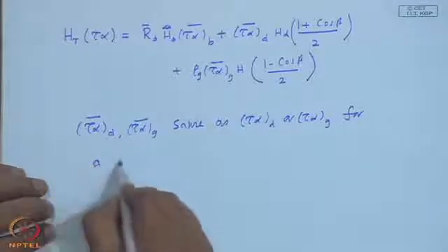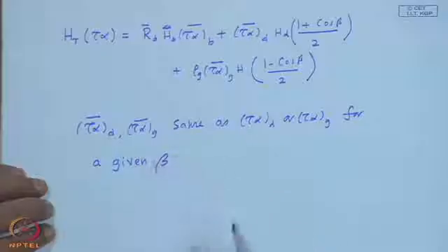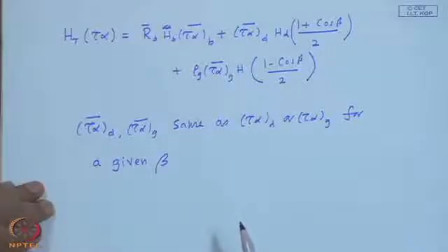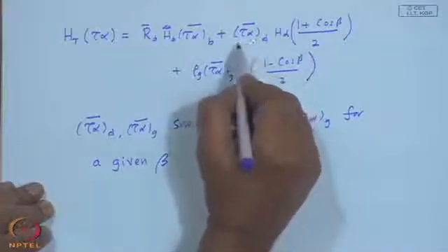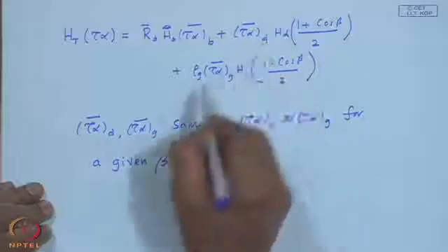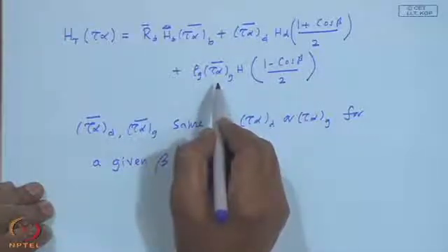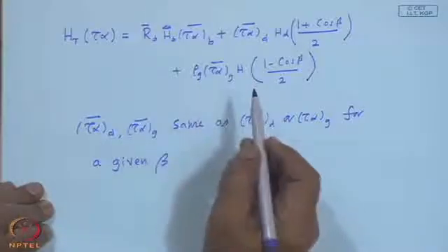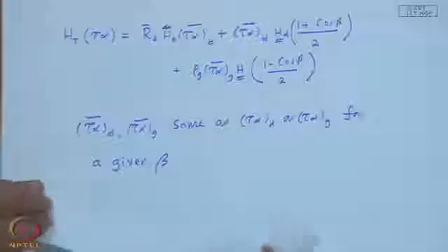for a given beta. Since it is only a function of slope of the collector, it does not change from hour to hour. So, the average daily transmittance absorptance product for the diffuse radiation or for the ground reflected radiation is a single number, which can be pulled out of my summation sign. Consequently, the summations will be H and H d over the day.